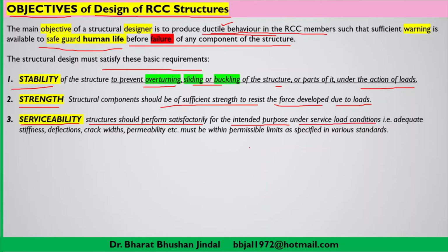That means it should have adequate stiffness. And if there is any deflection, crack width, or permeability, these must be within permissible limits. These permissible limits are clearly mentioned in various Indian standard codes, such as IS 456.